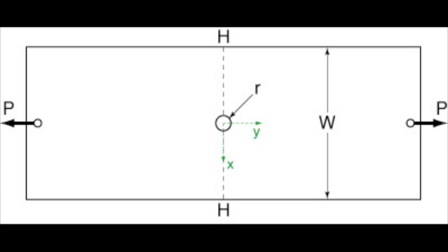In this lab, we studied stress concentration using a thin polycarbonate plate with a hole in the center. Here you can see the shape of the plate that was used in the experiment. Uniaxial loading along the length of the plate was applied on the plate. The HH line cuts across the cross-section with the minimum area.